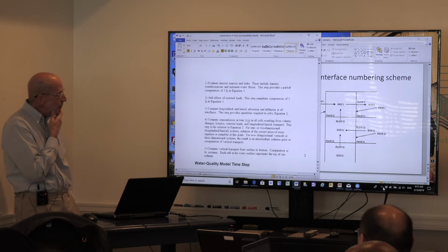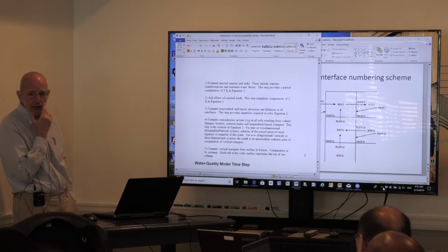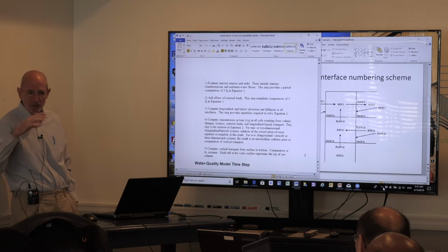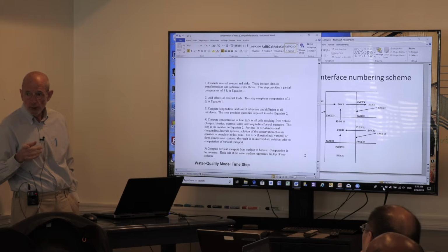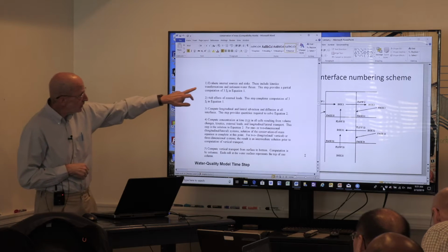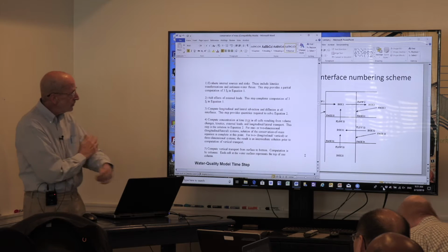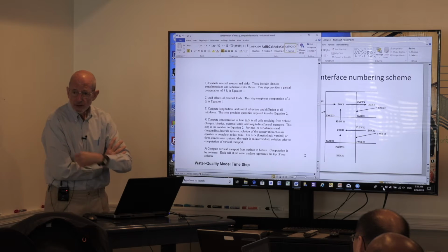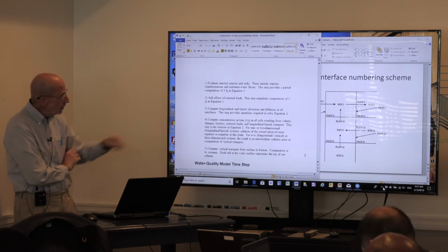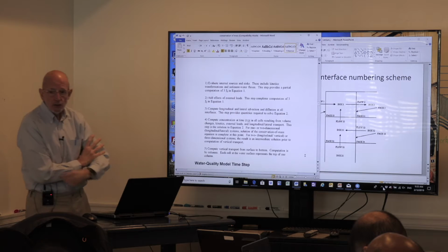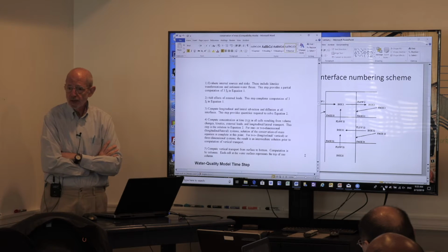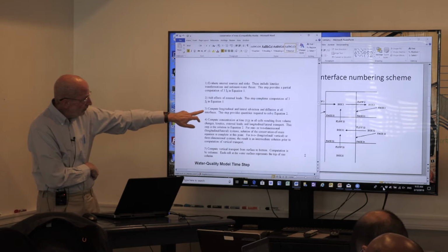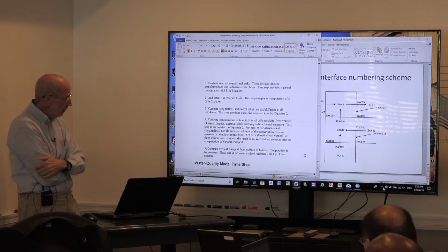So there's a summary, if you will, of how to solve this equation. Now, you don't really worry about this. The model code does this, but I'm just explaining to you what the model code is doing. First, it's going to evaluate the internal sources and sinks: the kinetics, transformation, the sediment water fluxes, these sorts of things. Next, we add in the external loads, the watershed, the point sources, these sorts of things. Next, we solve the longitudinal and lateral advection.